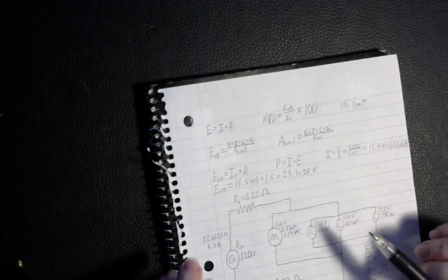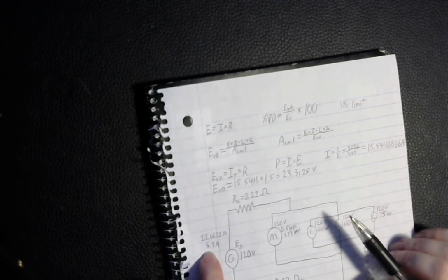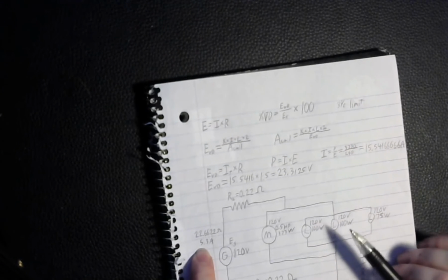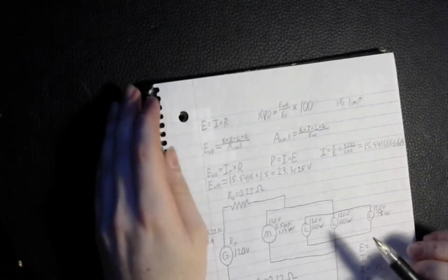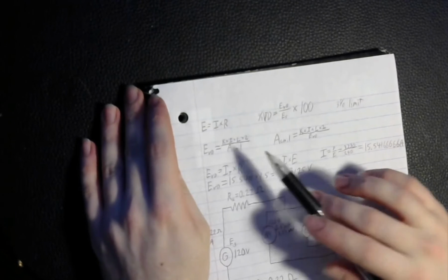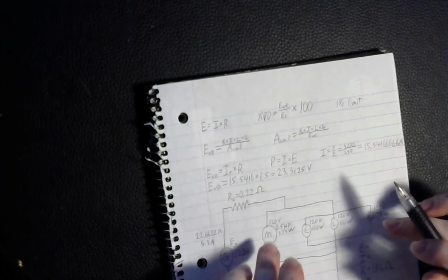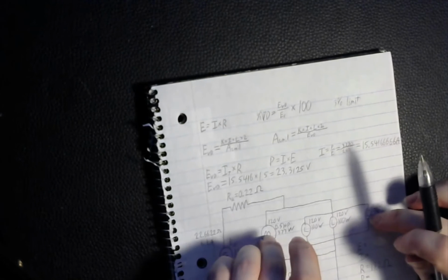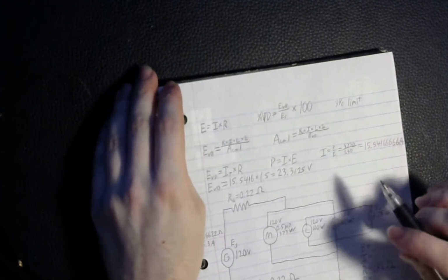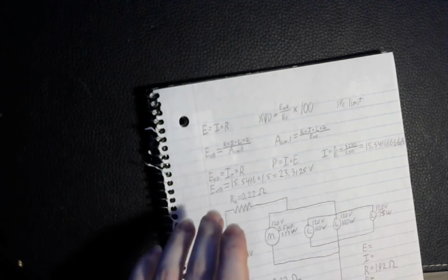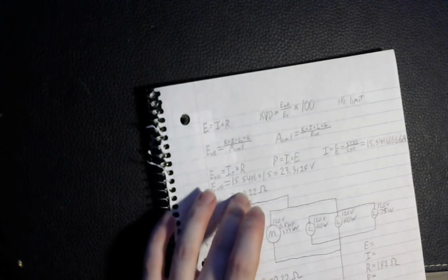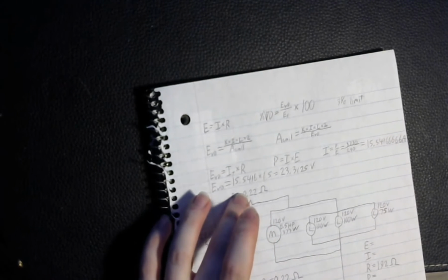Right. So what you basically need to do, once you've got your resistance and your current, actually no, for this part you just need the current. So your voltage drop between your source and your load, the formula for that is going to be your amperage multiplied by just the total resistance of just the wire.